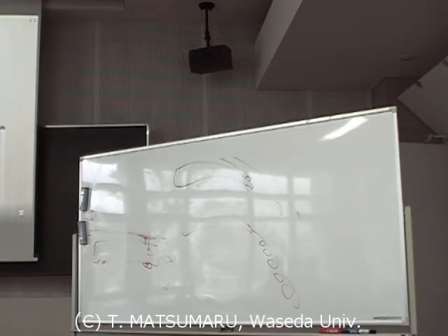Why does this occur? It is because you end up with something known as an inverse pressure gradient as you travel around the surface. This flow wants to continue going straight, this surface wants to pull it down. So you end up with a suction, inverse pressure. This will cause an eventual reversal of the boundary layer, which will then cause it to spiral around like that in what's known as a separation bubble, while the flow kicks over the top. This is largely due to the low energy level of the boundary layer, with respect to the high energy level up here, being able to pull this off the surface and keep going. This will only occur at a certain critical inverse pressure gradient, so it's defined by angles, things like that.